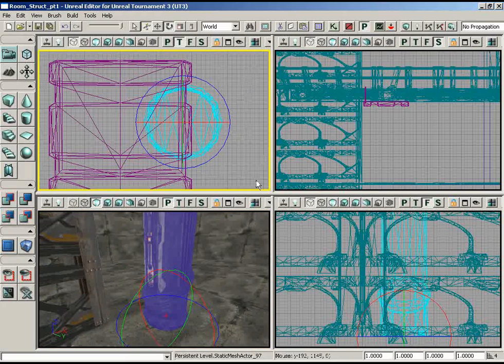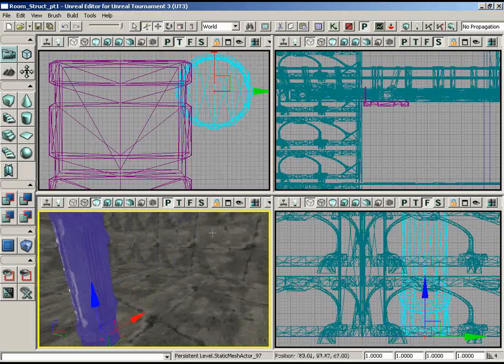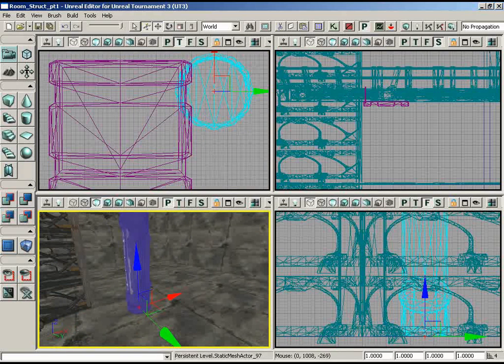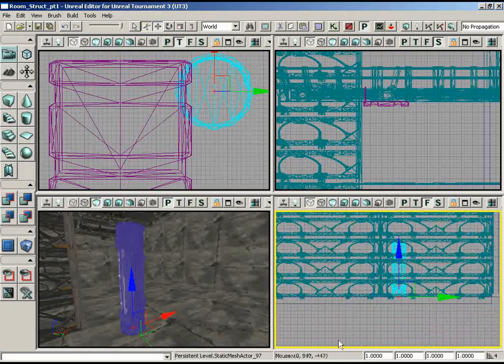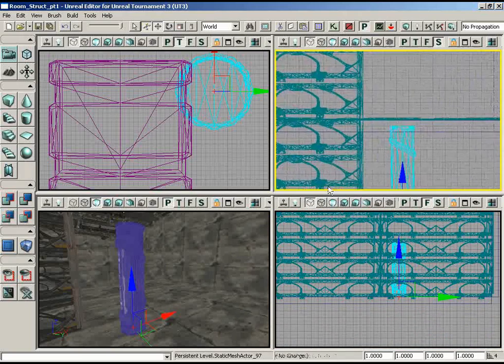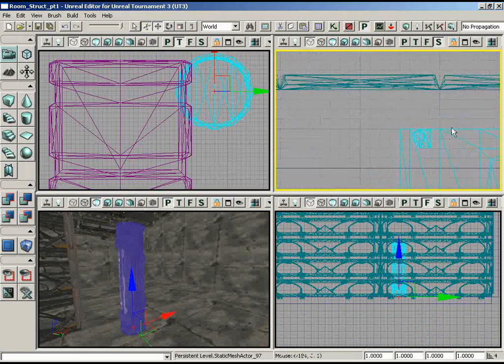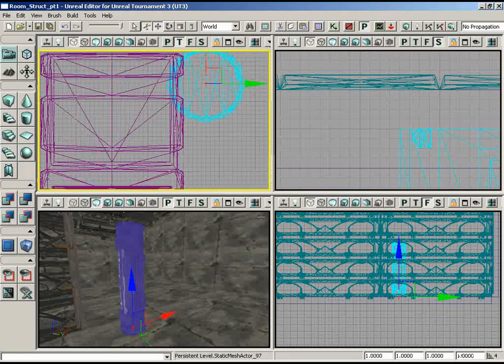And the next thing we notice is that the mesh is way too large. It doesn't fit into those grooves at all. Now, I don't want to mess around with the full draw scale, because it's important that the mesh be snappable in a front view, so that the next mesh, if we look at the grid line it lays on, has it lie on a nice grid line. So I want to leave the scale in Z alone. So I'm going to handle scaling in just X and Y in draw scale.